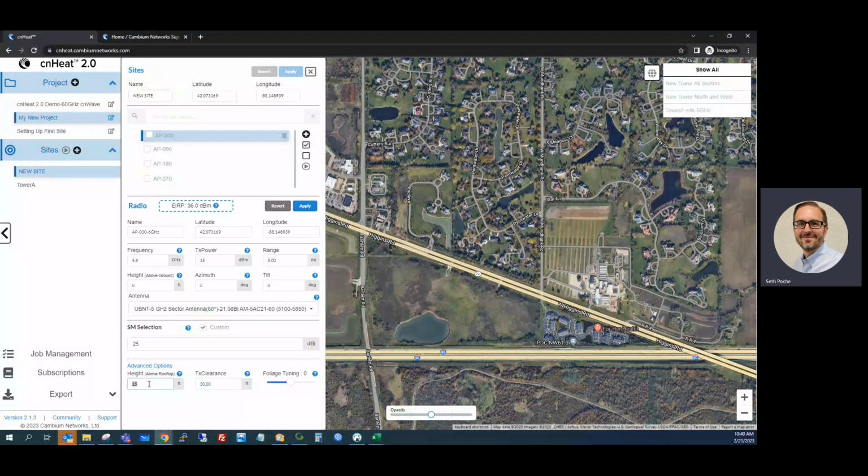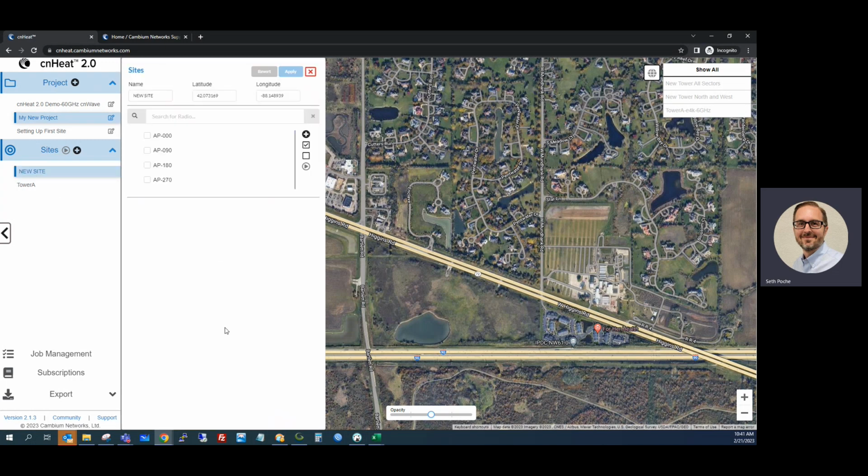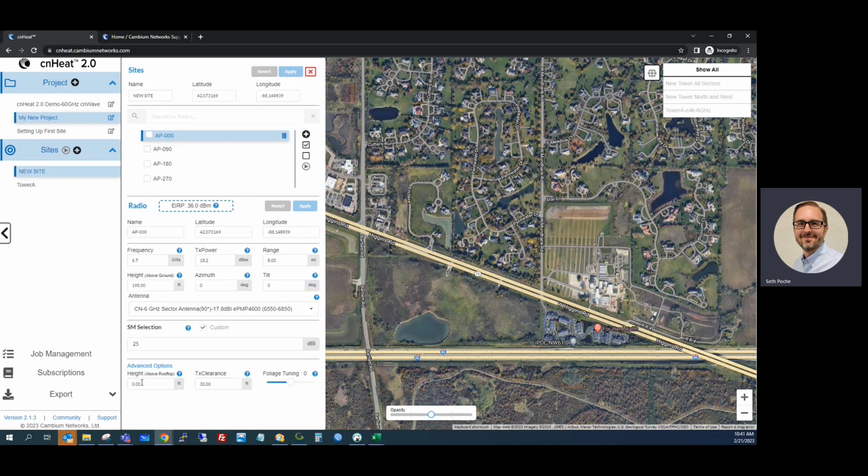This is the height above the tallest thing at that point. A lot of times customers will place the tower in a field, come over here and say something like 5 feet, thinking that this is the height above the customer install. And that's not the case. In fact, if you'll recall, we have a height slider for the customer from 0 feet to 80 feet. So please be careful. Please don't make that mistake. It's a very, very common mistake. But yeah, use this if you want to use the height reference and collider instead of a height above ground.